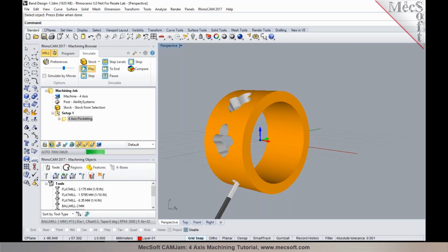So parts like these, toolpaths like these, can be programmed for parts that have a constant radius. And for the wrapping and unwrapping, the system computes based on the radius of the part. So the radius of the part geometry is known, and that's basically taken into account for wrapping and unwrapping.